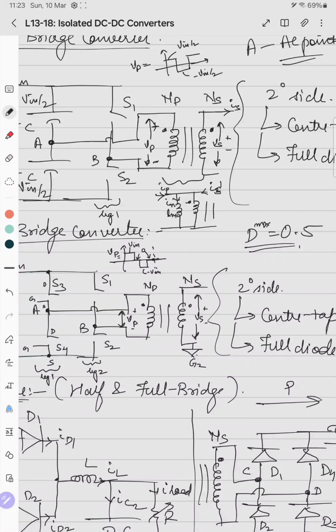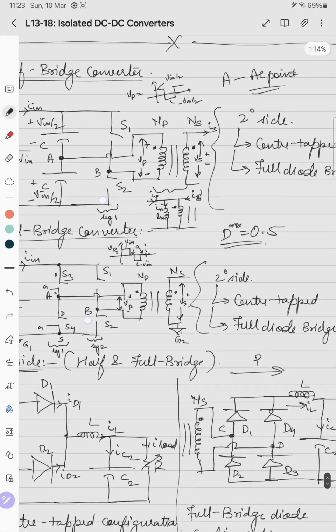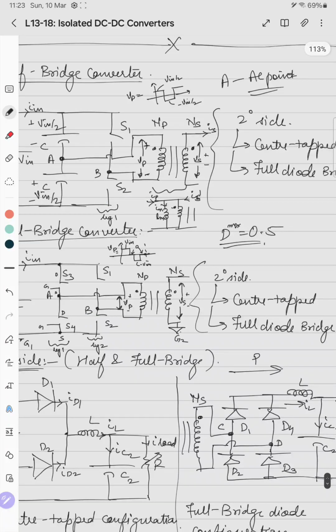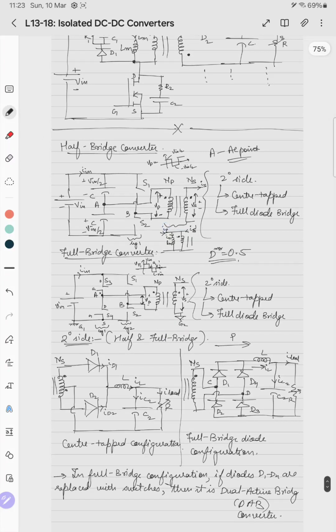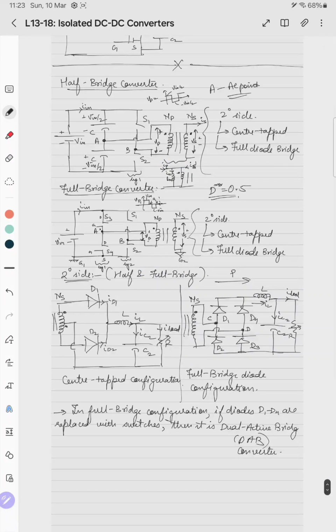So a half bridge converter is generally used in AC rectified output, where the capacitor bank is inherently used for filtering of the rectified voltage. That is the advantage of half bridge configuration. Then the flux walking capacitor should be used in all of the configurations, which is push pull, half bridge and full bridge, if in our control technique we do not take care of the flux walking phenomenon. So in case our control technique is very simple and it does not account for flux walking, we have to have a separate flux walking capacitor for those cases.